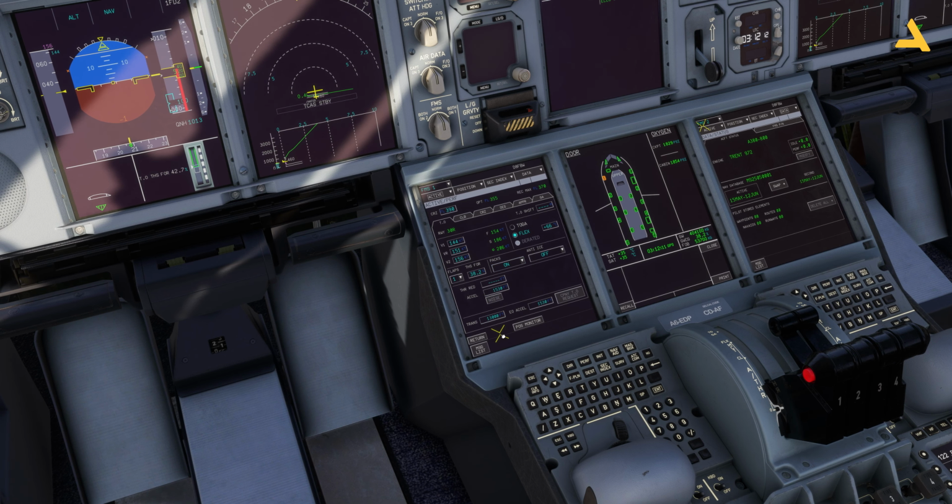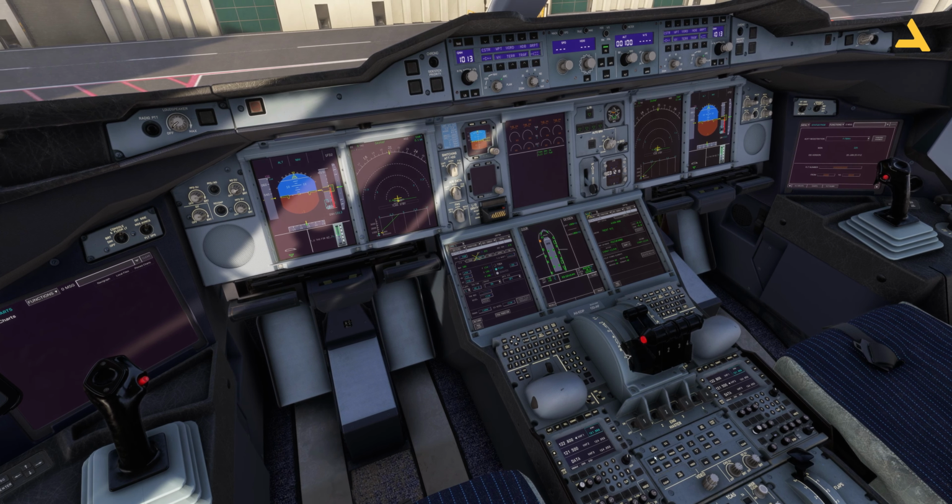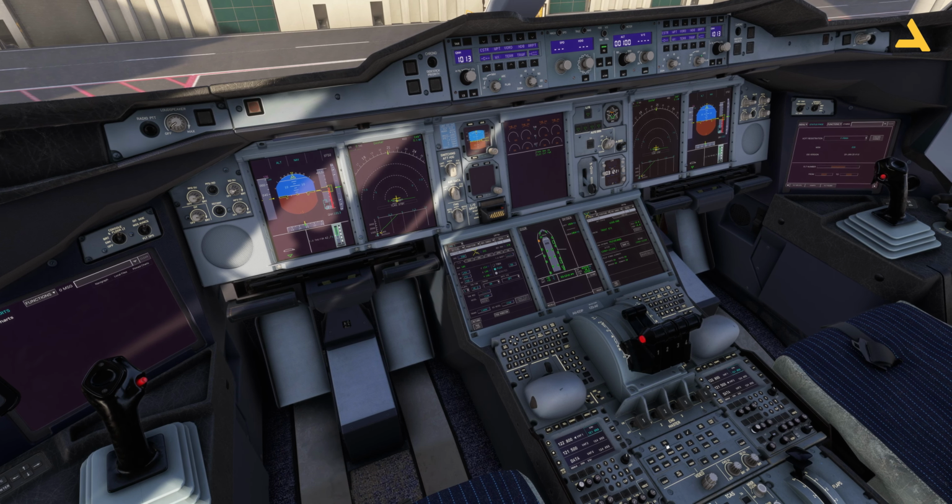So it's simple to actually configure the FMS. Now this plane has a built-in checklist. If you go over here on the pedestal, you will see this button checklist, and you can scroll through the items by using these buttons. So just go to this first option, cockpit preparation, and gear pins and covers removed, fuel quantity complete.